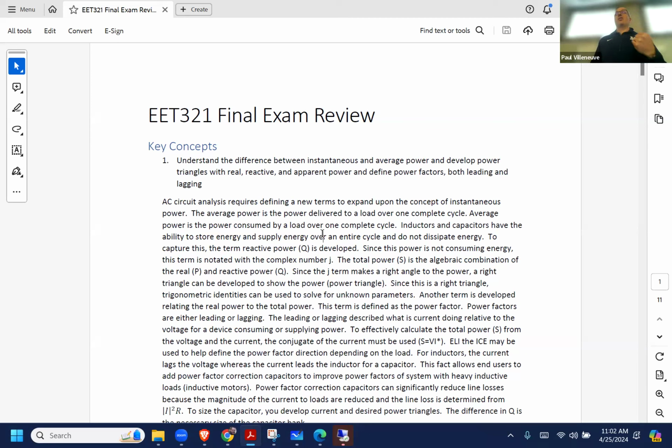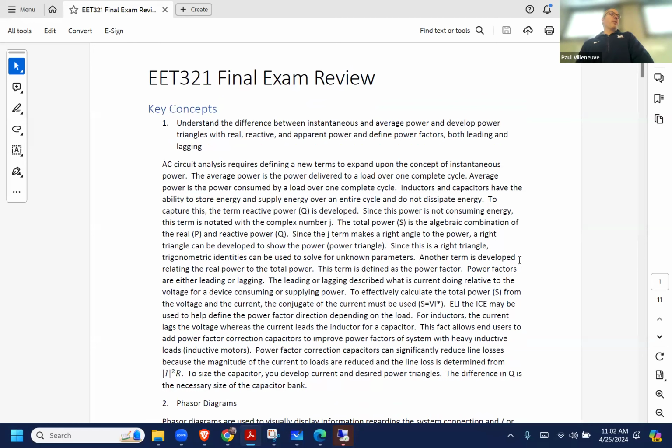Okay? It just so happens that RMS is a term we use because that's how the math works. So what is in your outlet is 120 volts RMS, not average, but RMS. If you did the time domain, what's in your outlet is 167 sin(377t), right? That's the actual time domain representation of that. So that was pretty important to us.